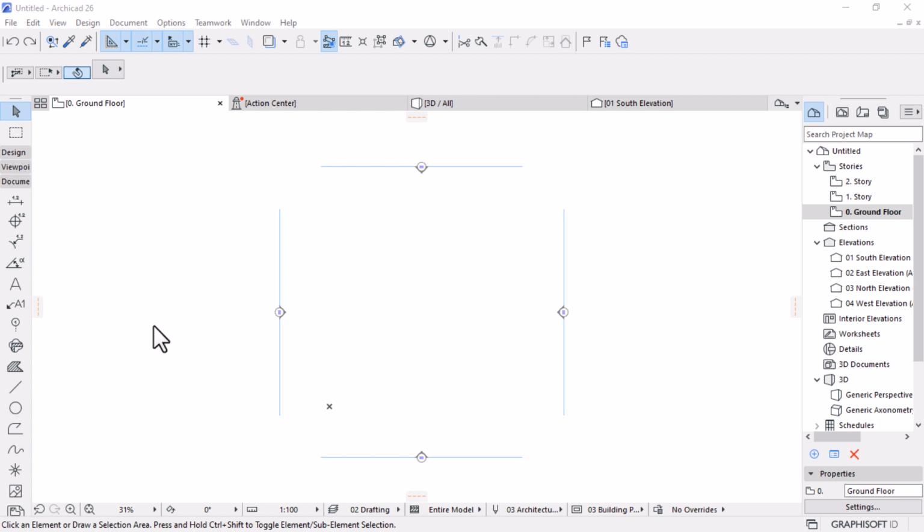All right, we're going to use a grid system to determine the position of our columns and beams, especially only structural elements. That's the reason why we're using grid systems. And it's always best to start with creating this structure, because you already know the design from your sketches. I already know how many grid lines I'm having on the horizontal line or on the vertical line.